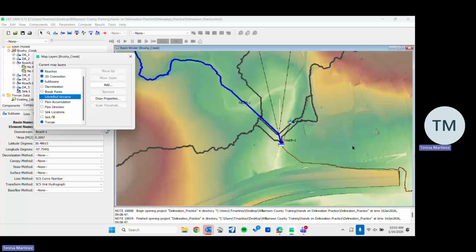So before we run this, I would probably do a terrain modification and punch through right here, so that when we run it, the model knows this is a low point, and the red line will come through here. But because we didn't fix anything here, when the model runs it, it sees there's an opening here, so it will take us that way.